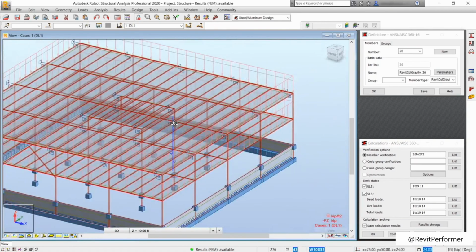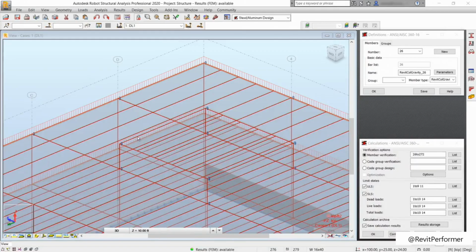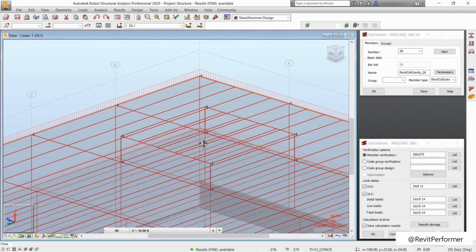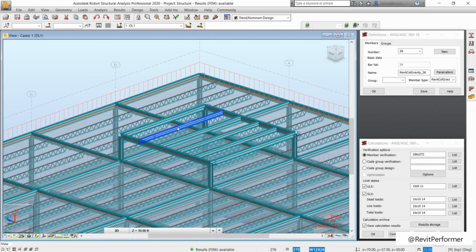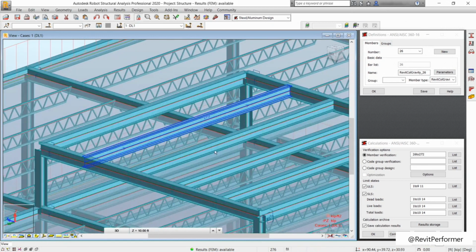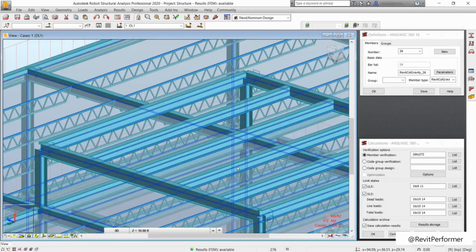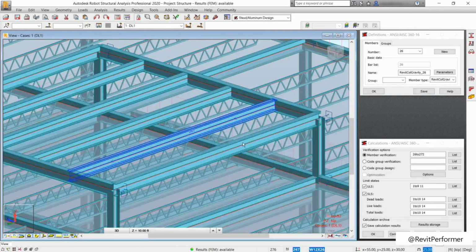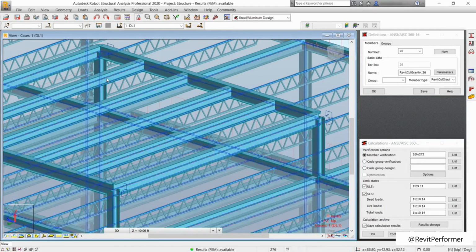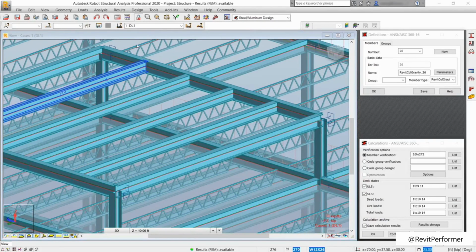So what I want to do is up here, if I hover over my beams, they're kind of hard to see because I need to see what numbers these are. So if I come down to my little control bar here and turn on Section Shapes, I'm going to hover over one of my beams here and I see it says 270, 69, 68, 67, 66. So now I can see these. I know that I've got 270 through 266. That's kind of important to know.